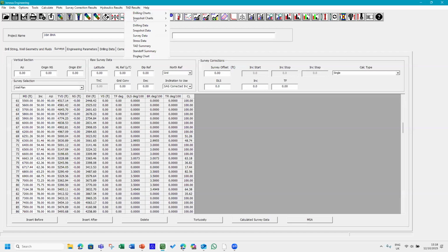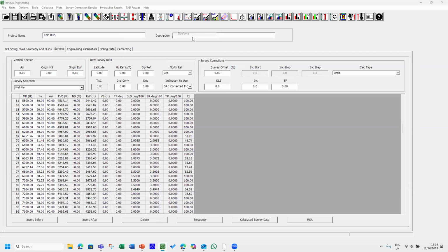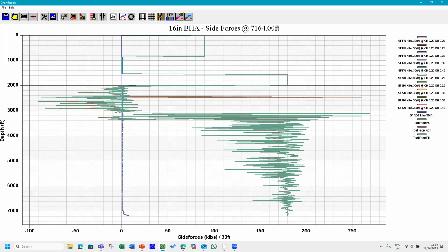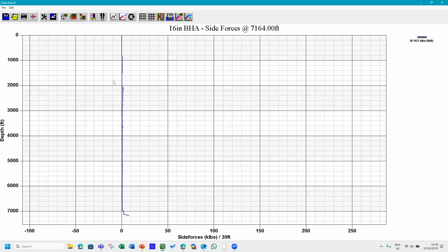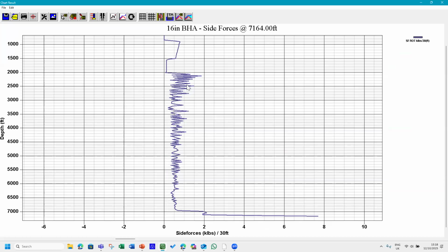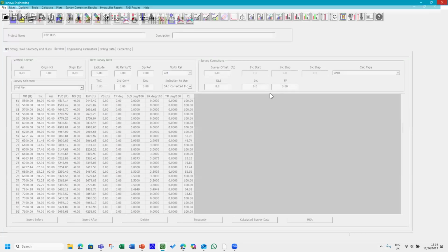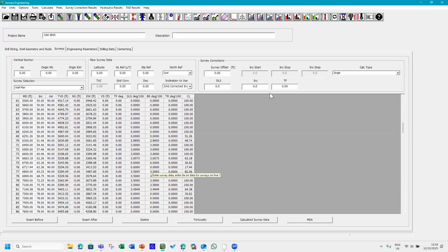And somebody might want to say, okay, how about the side forces, the casing wear and things like that? Maybe the casing wear could be something that we can sort out. We can turn off all but just the drilling load. This is the drilling load. It's not terrible. It's not going to eat up the casing. So you are okay for a lot of things, but you are not okay for cuttings transportation. You need a fluid technology, fluid adjustments, or some other stuff that we can probably talk about and explore.